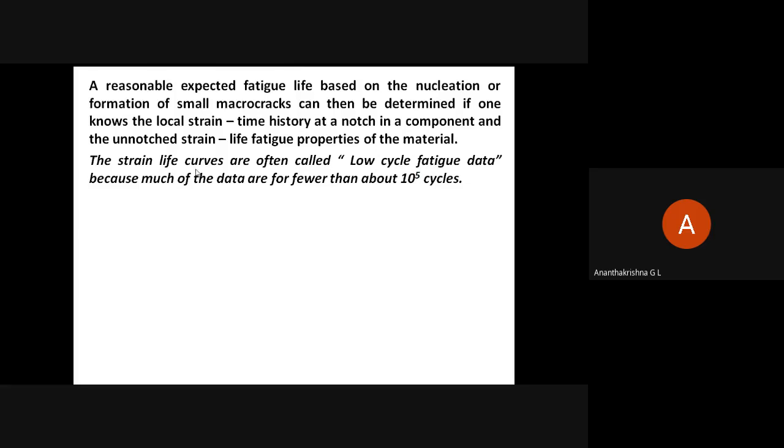Therefore, the strain life curves are often called as low cycle fatigue data because much of the data are for fewer than 10 power 5 number of cycles. So strain life curves, unlike stress life curves, are normally called low cycle fatigue data. That is the failure that has happened before 10 power 4 or 10 power 5 number of cycles. Okay, please note down this last sentence. The strain life curves are often called as low cycle fatigue data. Please note down this sentence which is written in italics.